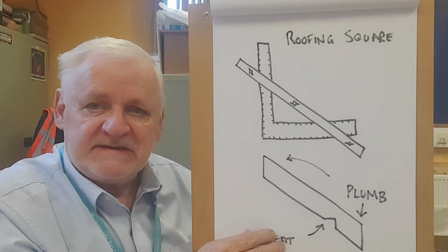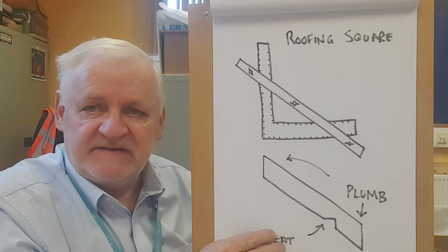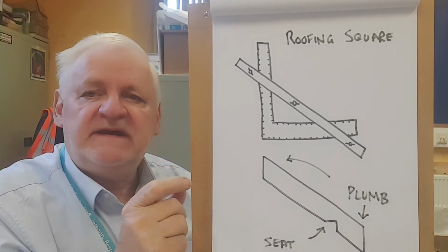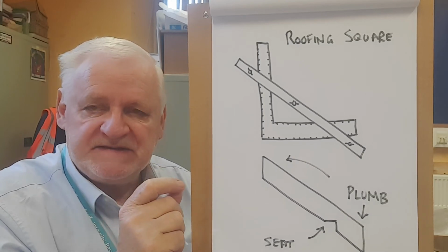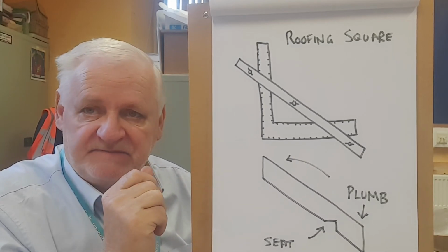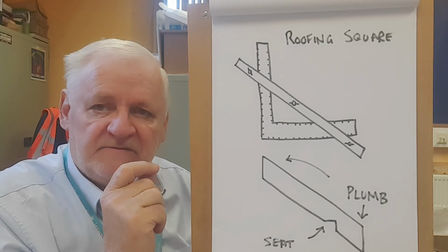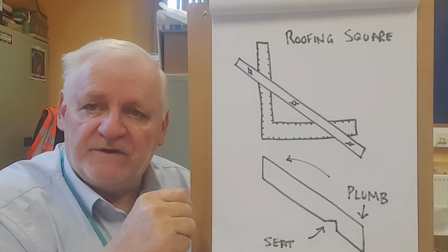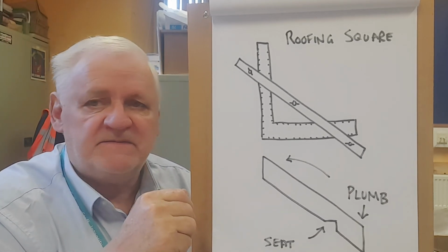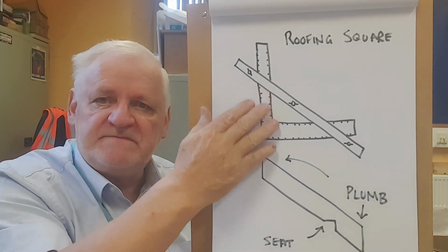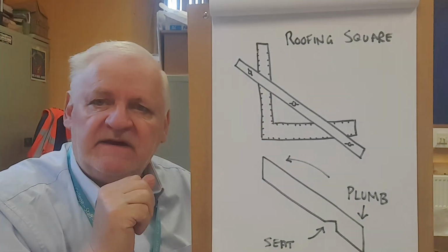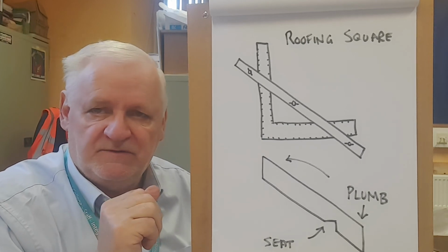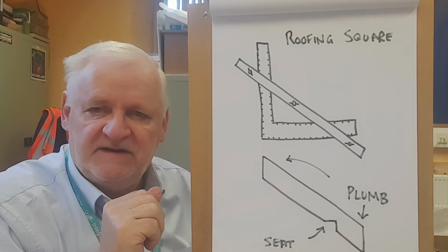Now then, some of you may be saying, I'm confused now, Stephen. I understand. Learn to make a cut roof doing it in a real size set out. Always do it in a real size set out. Use the whole of the wall plate as your full size drawing, and that to me never fails. All of these methods can be slightly difficult, slightly confusing, but when you do it on a full size drawing, then you'll find you'll understand it perfectly well.